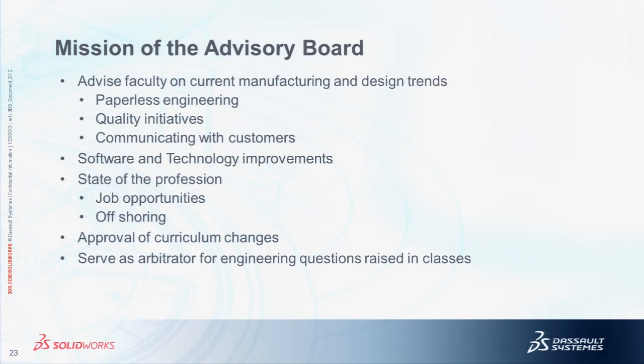We had one on this one, which I thought was interesting. We had a press fit situation, and the bushing ended up flush to the bottom of something. And the question is how do we document that? Do we just say press to flush? I can't find anything in any of the ANSI stuff about that. So I sent it out to the advisory board, and somebody came back, sure enough, that said, yeah, you should probably put a dimension in there, maybe a dimension of 0 or whatever it takes. And I like that kind of feedback coming from industry, that, okay, this is the way we would do this. Not just guessing and making up what you want.